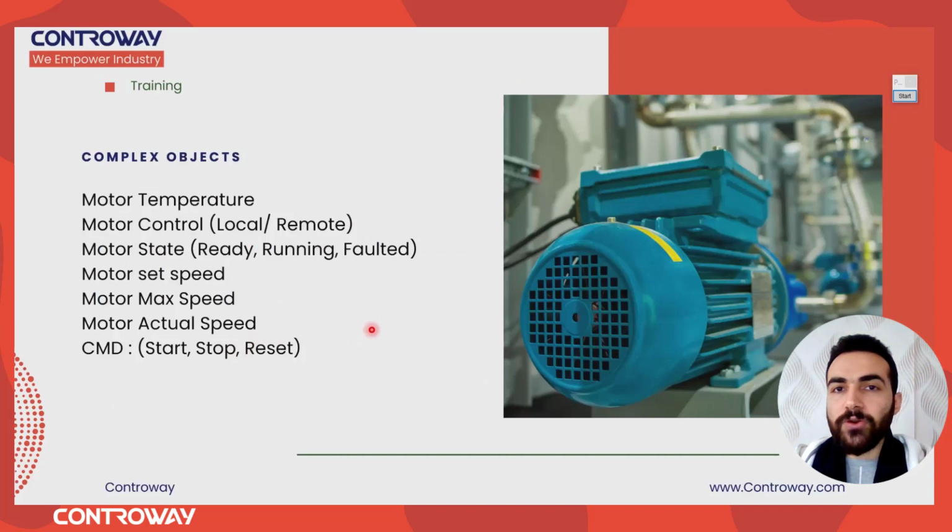But if you have more complex objects, something like a motor, a tank, a mixer, here you can define, for example, for only one motor, I can have a lot of variables, like temperature, speed, the control mode, is it local or remote, the state, is it ready, running, or faulted, the set speed, the maximum speed, the actual speed, and the command, I can give it start, stop, and reset.